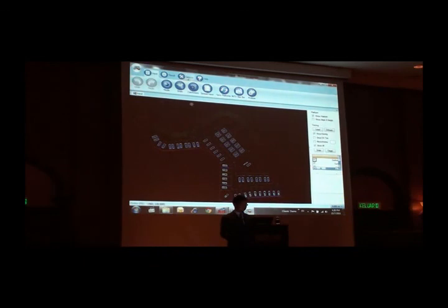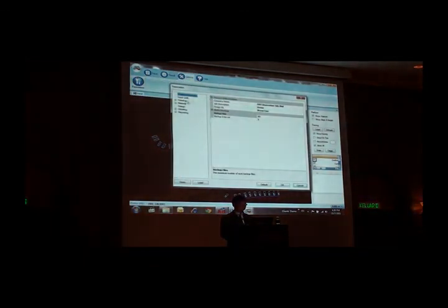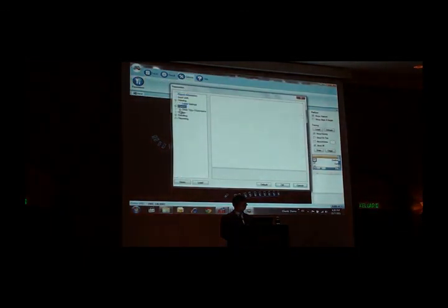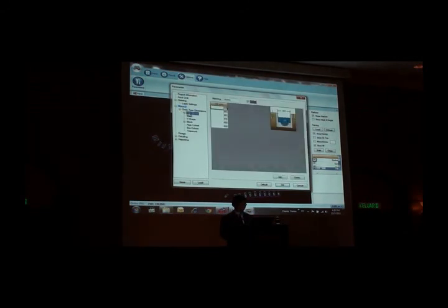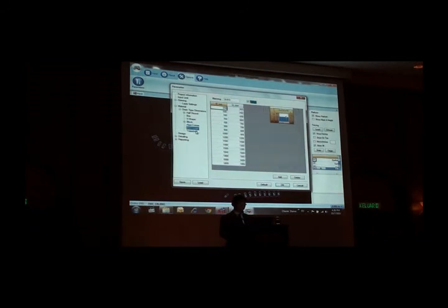Okay, so before this, we can check the parameter setting. We have 7 types of drainage channel design: half round, box drain, V-shape, broad drain, pipe covered, box covered, and trapezoid. Okay, so we can set rules for the program to do the iteration. Let's say for the box.